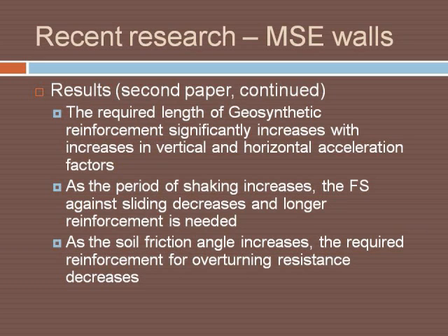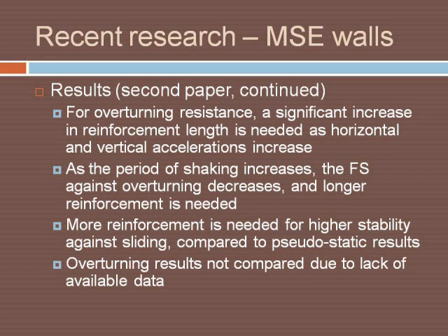They also found that as the period of shaking increases, the factor of safety against sliding decreases and longer reinforcement is needed. And they also found as the soil friction angle increases, the required reinforcement for overturning resistance decreases. We can also see that more reinforcement is needed when horizontal and vertical accelerations increase, as the period of shaking increases. And we've also noticed that overall, this analysis method requires more reinforcement compared to the pseudo-static results.